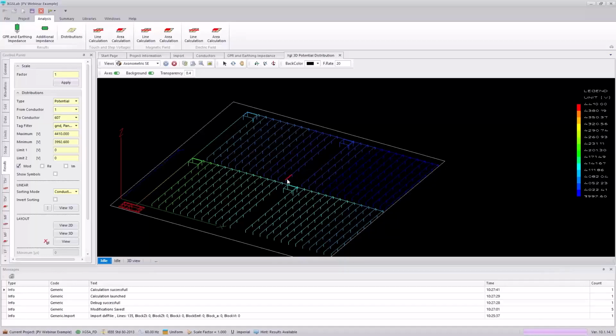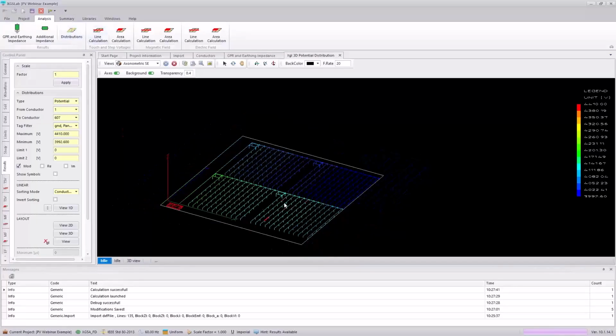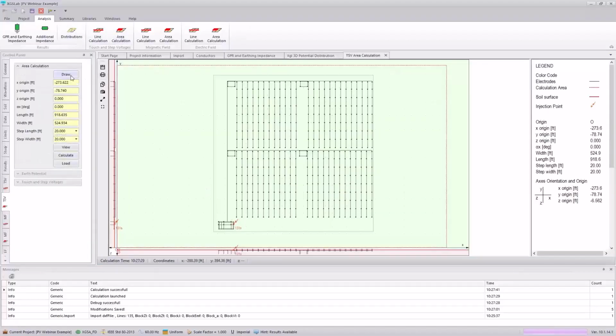So really what we want to make sure is that tools are accounting for the self-impedance and mutual impedance so that they consider the voltage drop when you're looking at large photovoltaics. And even this, I would consider not a large photovoltaic. This is what I would say a medium size or small. Most photovoltaics now are going to have many times this dimension. So you'll see this issue more prevalently on even larger systems.